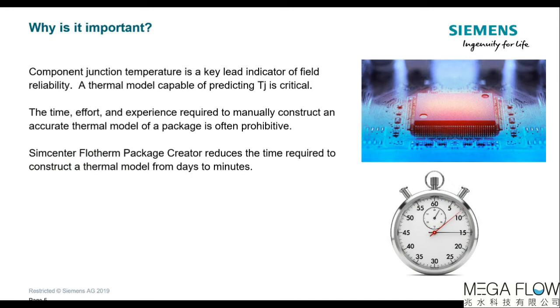Probably the most important thing to derive from a simulation is the junction temperature, as this leads to development of reliability predictions. The more accurate the thermal model of a package, the better the prediction. However, using traditional methods to create the component models to high levels of detail is extremely time-consuming. Simcenter Flotherm Package Creator is designed to reduce these timescales from days to minutes.